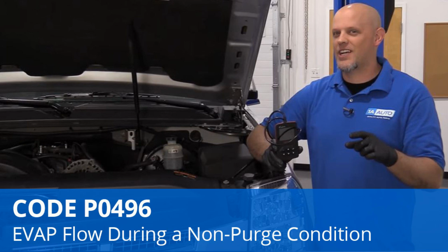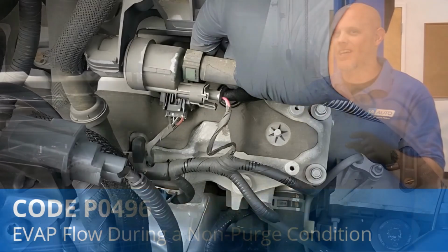How to diagnose P0496? Diagnosing the P0496 code can be a complex process due to the variety of possible causes. Here's a general guide to help you diagnose the P0496 code. Scan the OBD2 system. Use an OBD2 scanner to read the P0496 code and check for other associated codes. This may provide additional clues to the problem.